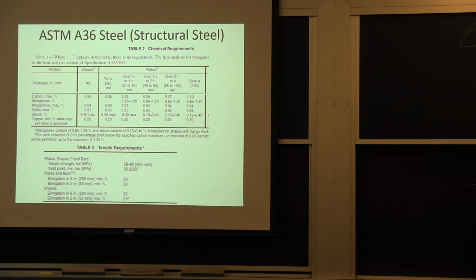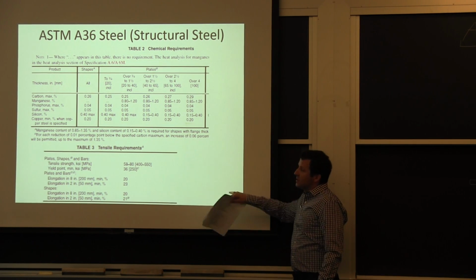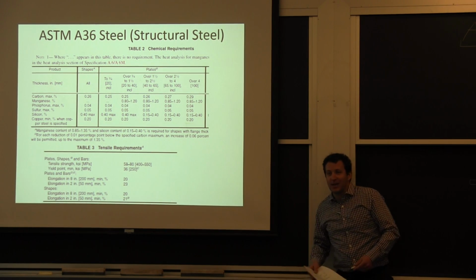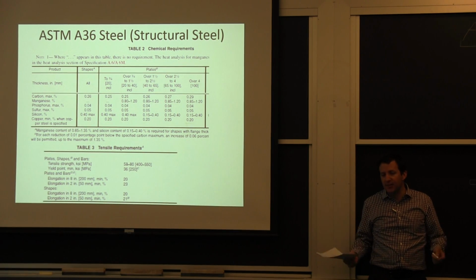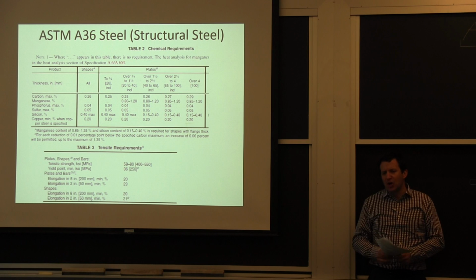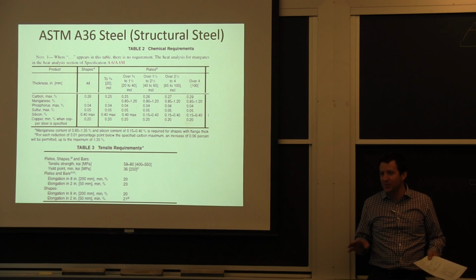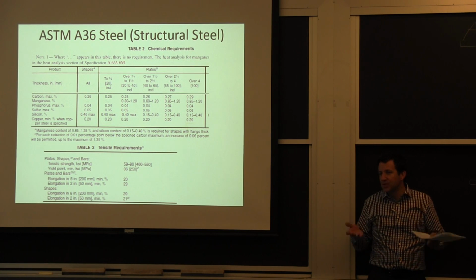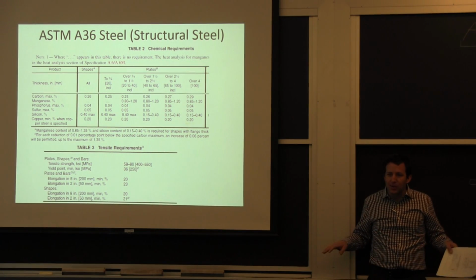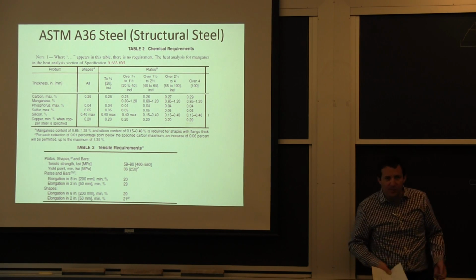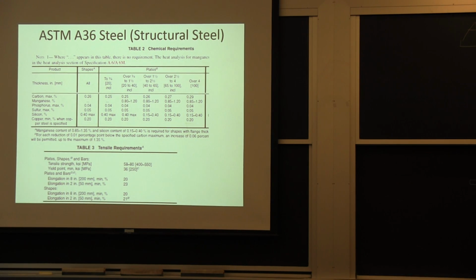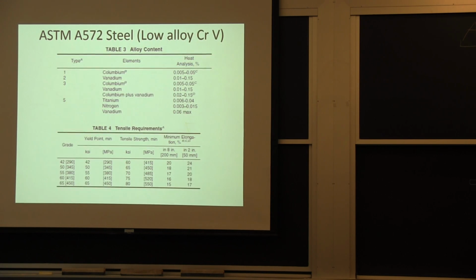Now, you can use it, but the properties you get out of welding this steel are the lowest. And I never really tried to take a steel that I didn't have a mechanical sample to say, oh no, this is not grade 36, this is grade 50. I would need to have the data to boost it up. But to say, okay, we're gonna take it as A36, if it has all the chemistry requirements, was something that I've done day in and day out.